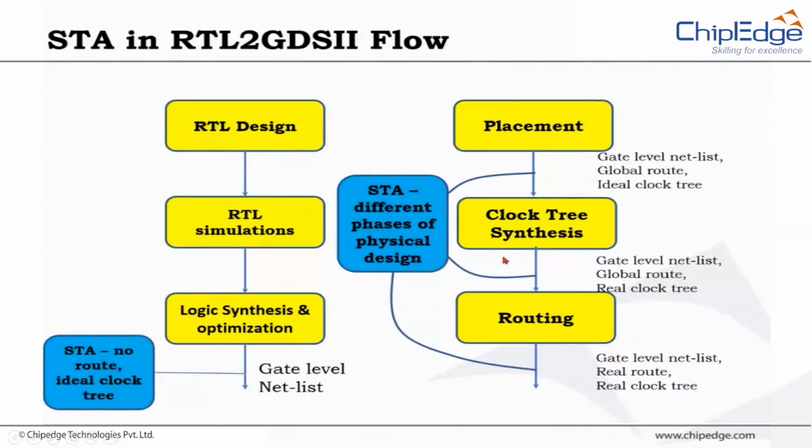Clock tree, like we have covered in some earlier classes, is all about buffering your clock. See, your clock has got a huge fan out. If you were to think about it, the two signals which will have a heavy fan out in your design are really the clock and the reset. Because the clock goes to every flip-flop in your design. Right? So suppose your design has got 1000 flip-flops. Your clock pin is seeing a fan out of 1000. And imagine the kind of load that is sitting on a line with 1000 endpoints.